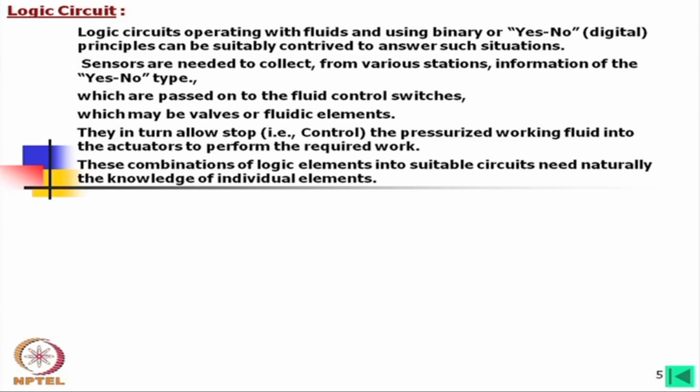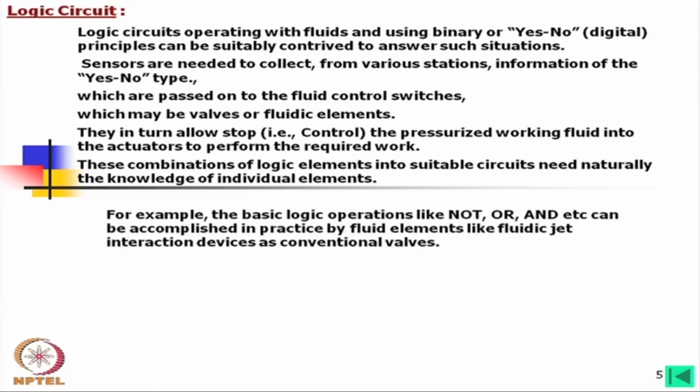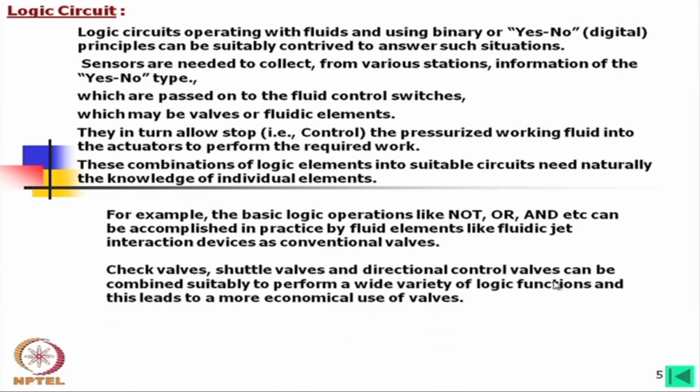These combinations of logic elements into suitable circuits naturally need the knowledge of individual elements. For example, the basic logic operations like NOT, OR, AND etc. can be accomplished in practice by fluid elements like fluidic jet interactive devices as well as conventional valves.